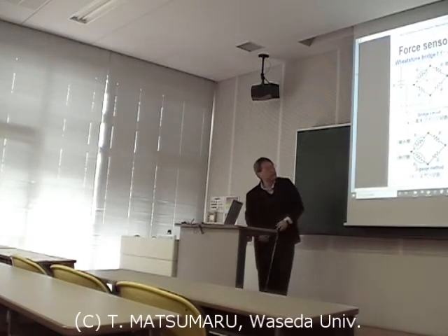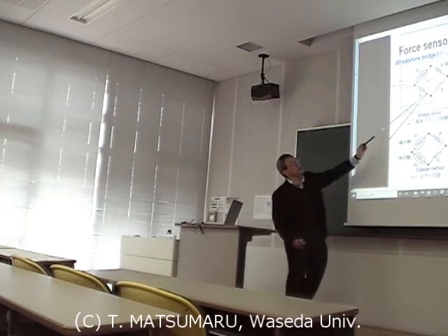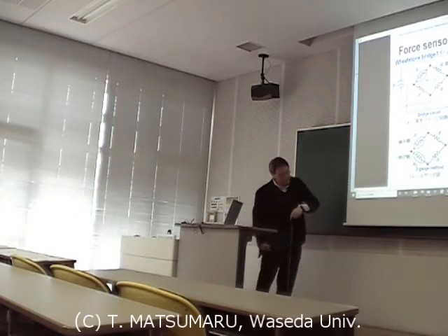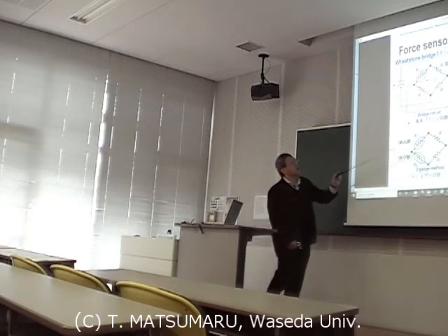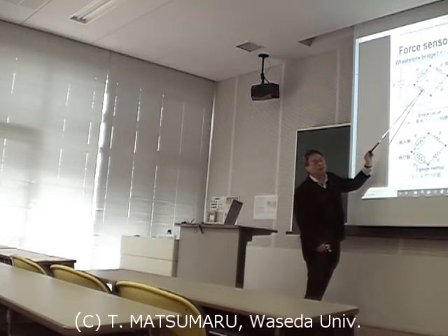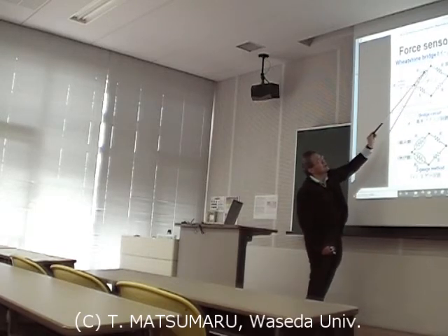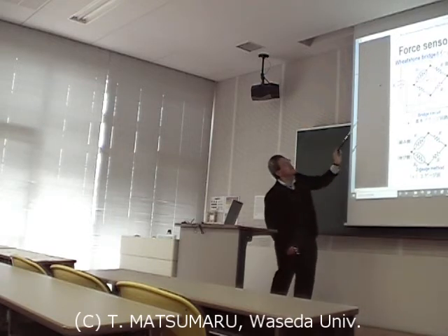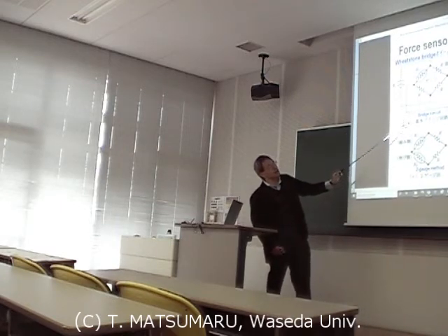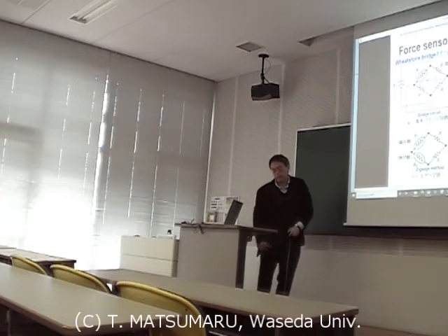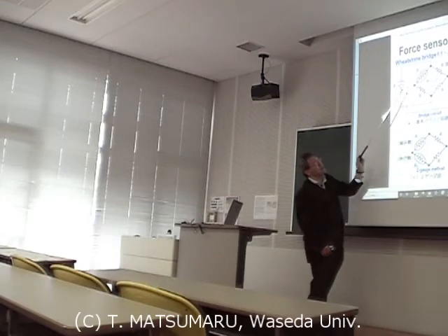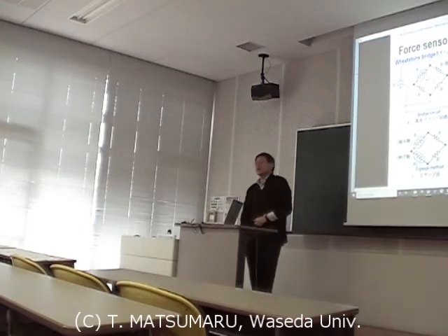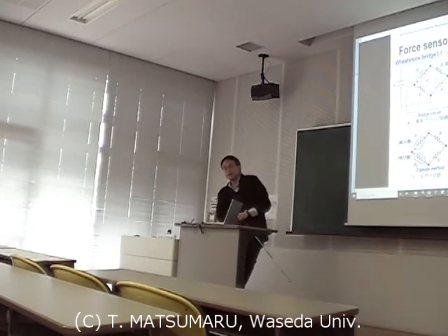Maybe in your high school days you have learned about the Wheatstone bridge. With fixed resistances, this resistance is slightly changed, and then by using this bridge circuit, this slight change is detected as a slight output voltage change.